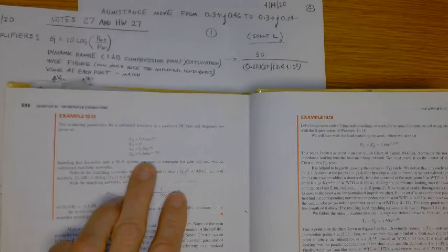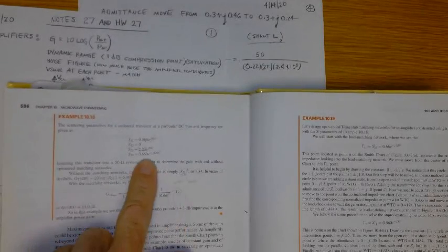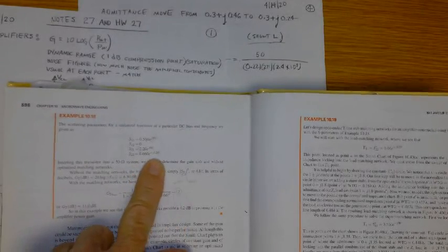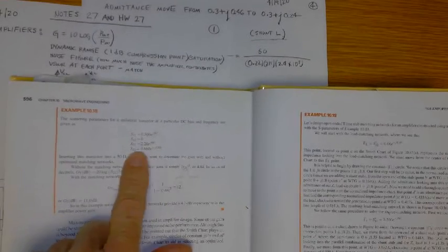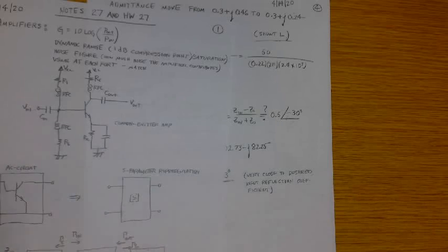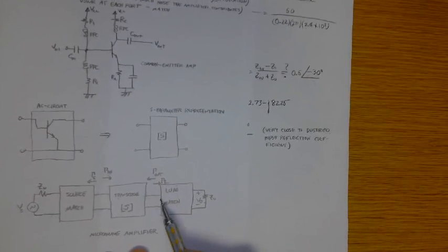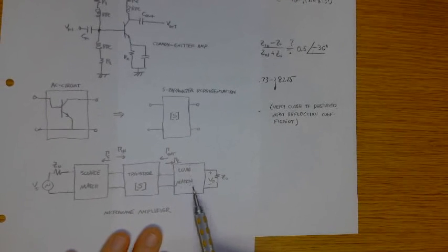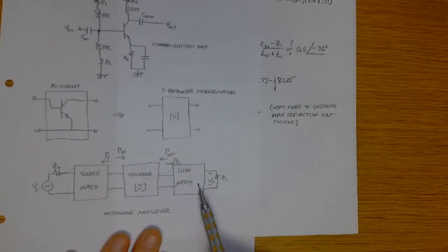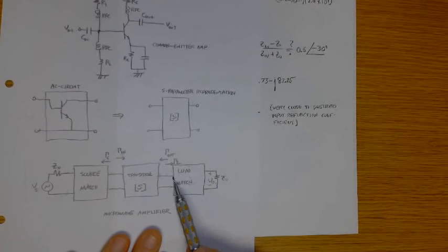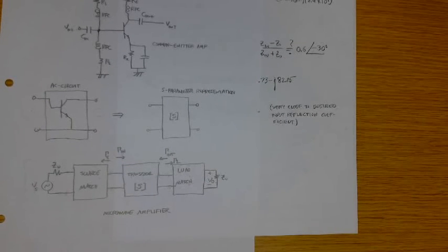So it needs to be 0.66 at an angle of minus 120 degrees, conjugate. So looking into your load matching network, you need to verify that after you put in your L's and C's, your lumped elements, you get a reflection coefficient here of 0.66 at 120 degrees.